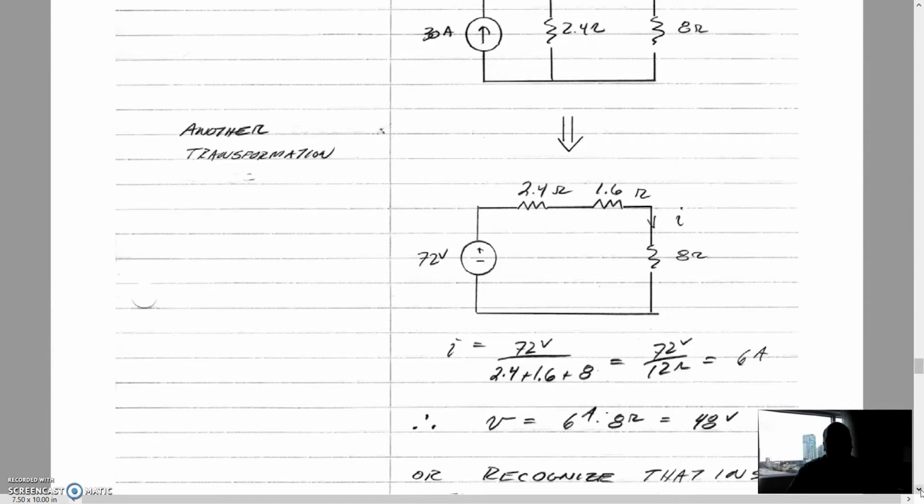So anytime you're solving for overall power in a circuit, doing these series of source transformations is not going to be helpful, because essentially you're going to be getting rid of the thing you were trying to solve for the power for. So overall power, those sorts of things, you've got to just do the old-fashioned way, doing a mesh current or a node voltage, and then just calculating the power for every source or for every resistor.